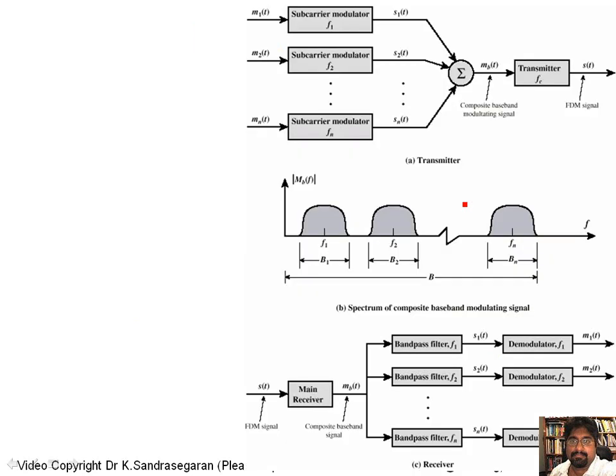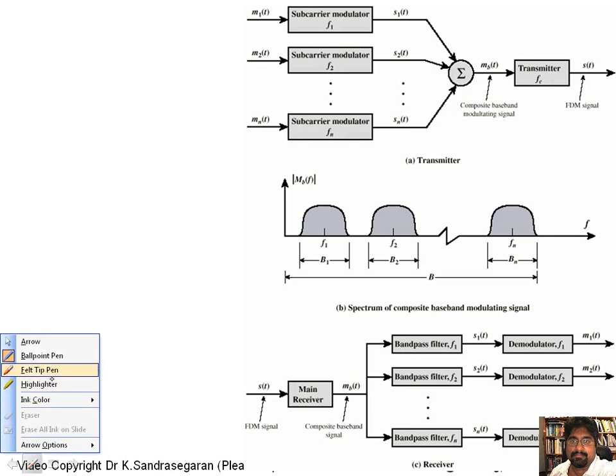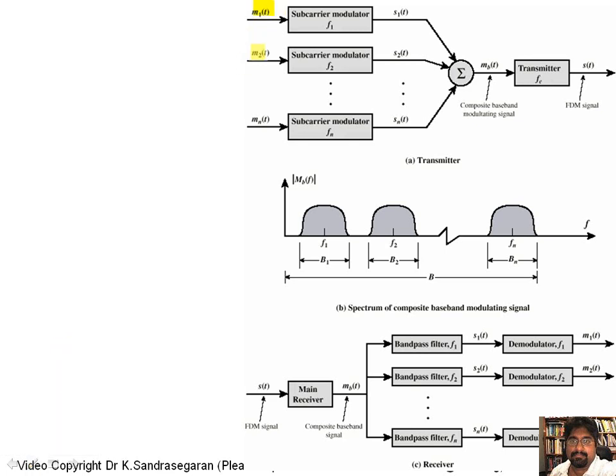Okay, here's an example of how frequency division multiplexing has been implemented. Now this particular slide is not from the Schiller text, it's from Stallings, but essentially I put it here to demonstrate in reality how frequency division multiplexing is implemented. So you've got a number of users here. You've got user M1, another user M2, another user M3, up to Mn. Each user is modulated by a carrier, and we'll talk about modulation shortly.